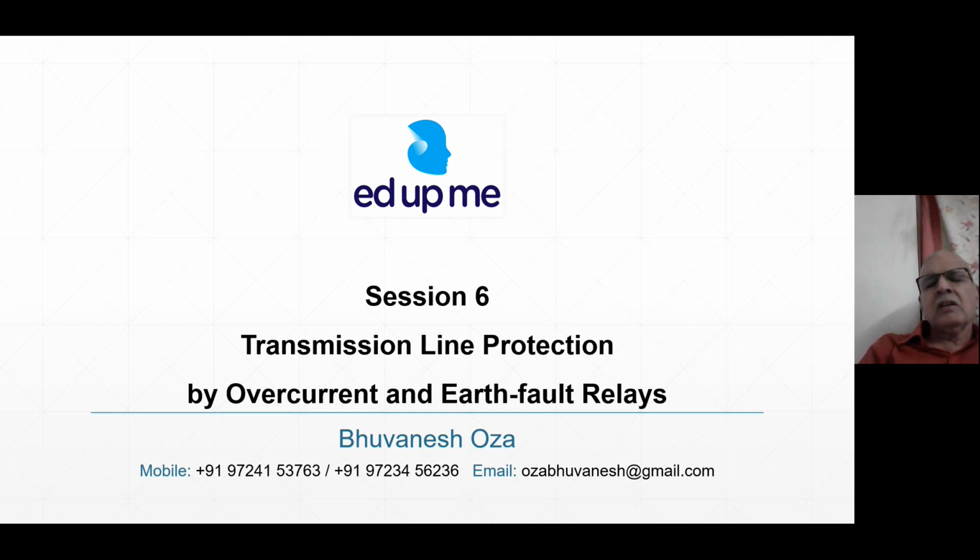That is, the relays we use are IDMT over current relays. But in IDMT over current relays also there are 17 different types of characteristics. Let us not talk about all 17 right now because it would be too much, but at least 4 very important characteristics: normal inverse IDMT, very inverse IDMT, extremely inverse IDMT, and long time inverse IDMT.